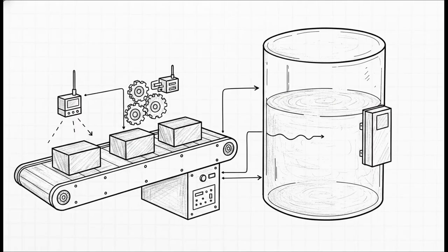To put this into perspective in the real world, you're going to find inductive sensors serving as the absolute backbone of heavy industry. Because they are so incredibly reliable at detecting metal, they run automated manufacturing lines, manage collision detection, and handle speed sensing. Capacitive sensors, on the other hand, are the versatile heroes of tricky materials. Since they can detect nonmetals, they're heavily used for level sensing and liquid detection, especially in harsh environments. In fact, you'll constantly find them inside automatic pump control systems, diligently detecting water levels.